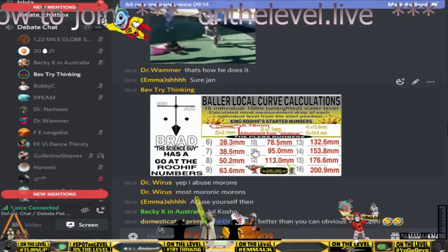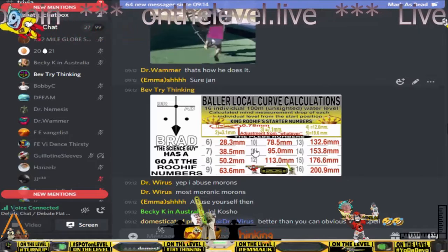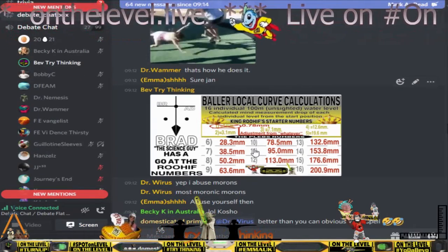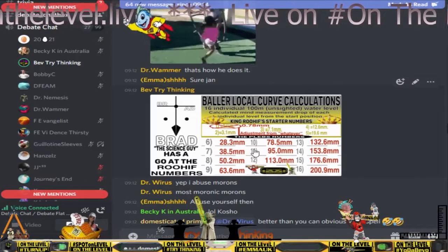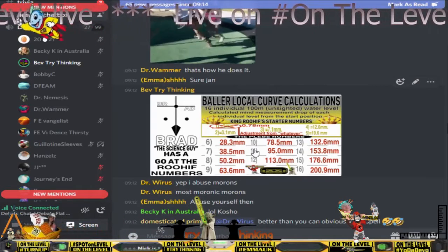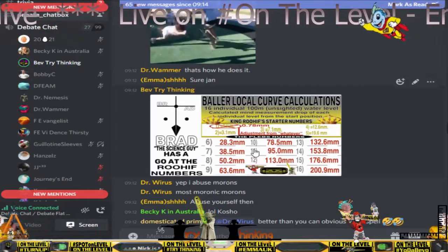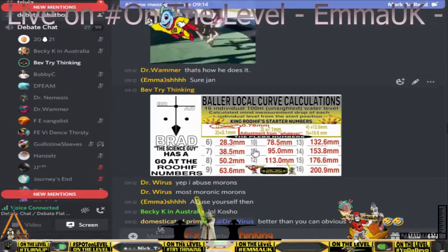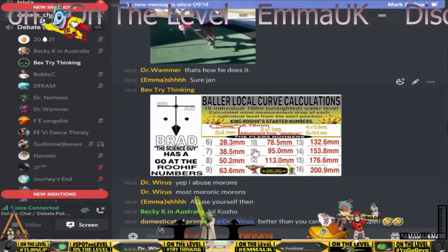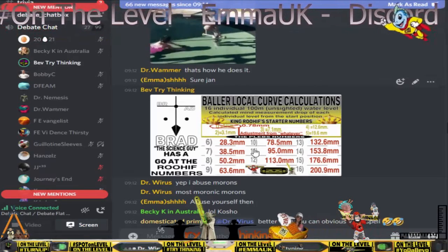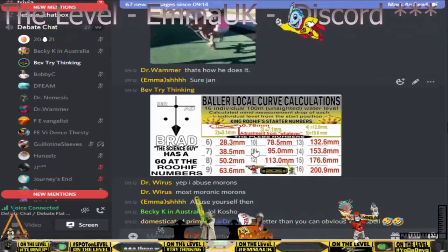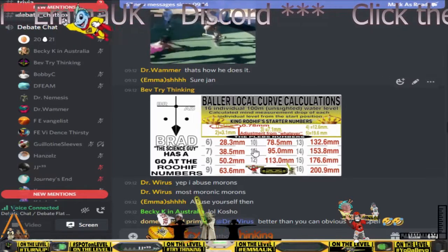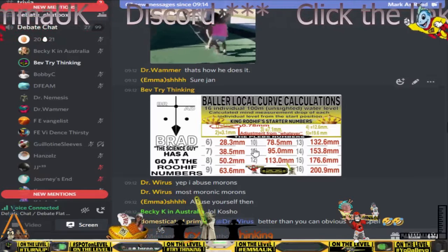Okay, so let's say at 400 meters, if we had a 400 meter tube, according to that there should be a 12.6 millimeter drop at 400 meters. But that's obviously not there, is it? Can't be. So we have to take the midpoint, which is written down here as a drop, but because we're leveling that total distance off, the half distance would be the sagitta.